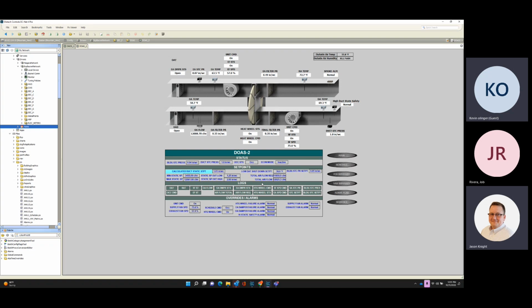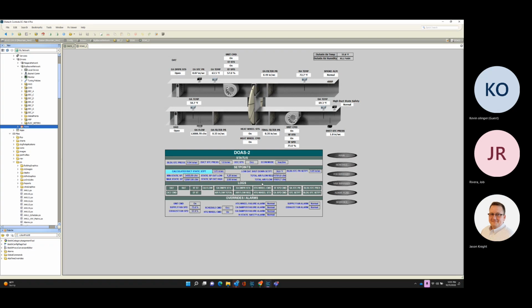Right. So now it's demand control only. We only care about getting enough fresh air for COVID and CO2 levels into this building. So we're looking at what every one of those boxes actually needs and then resetting based off of that.